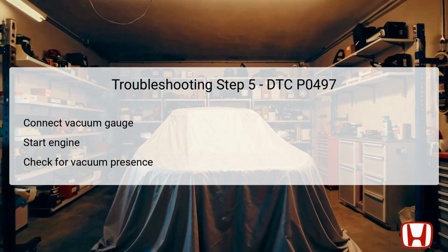A lack of vacuum could indicate that there are blockages in the passages that connect the intake manifold to the valve, preventing proper operation of the EVAP system. If vacuum is confirmed, you will advance to checking the fuel tank pressure sensor in the next step.